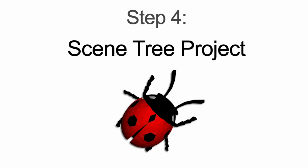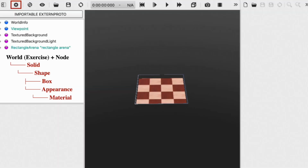Step 4. Scene Tree Projects. In this example, we will stop at the Scene Tree Project stage and create a simple world exercise. We start by adding a solid shape node, such as a box, and then assign an appearance to it by applying materials. This allows us to build the basic structure of the scene, while learning how to work with objects, their properties, and the scene hierarchy.